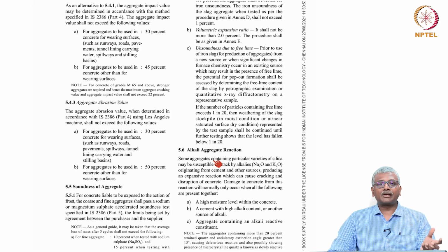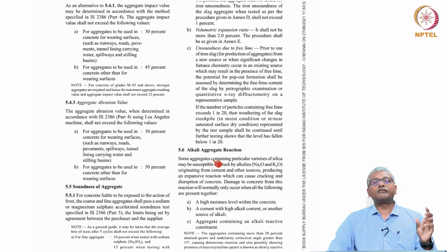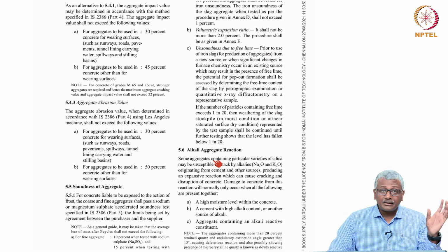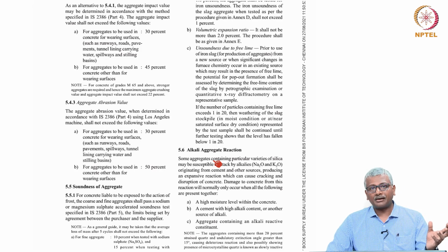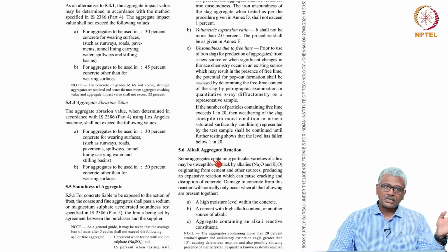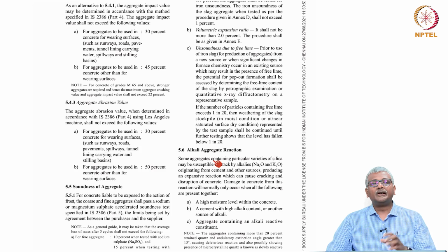Of course, in recycled concrete aggregate, if you know the provenance of the aggregate that was used in the old concrete, you can then be fairly certain that aggregate will govern the ASR potential of this aggregate. As long as the original aggregate was okay, you will not have any problems with the use of crushed recycled aggregate in new concrete.